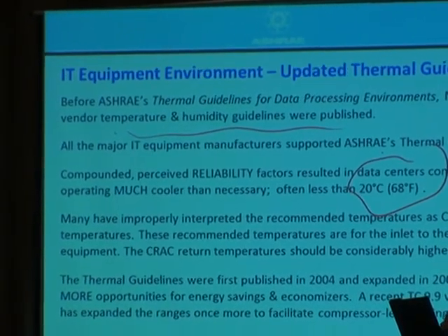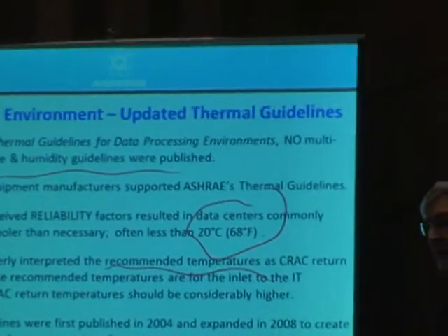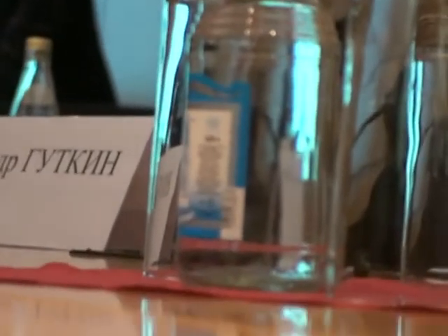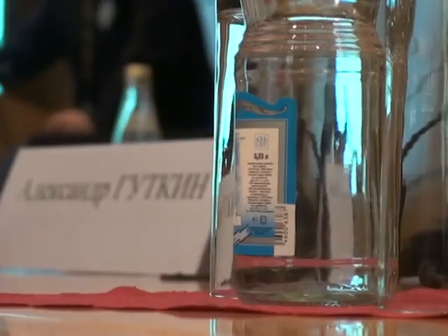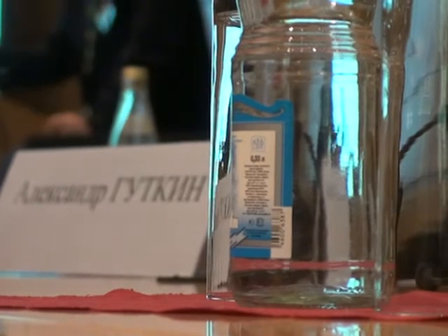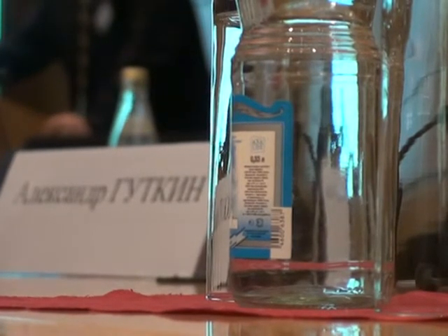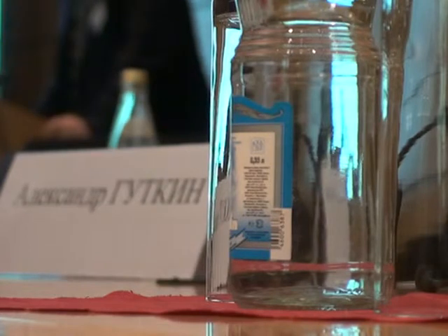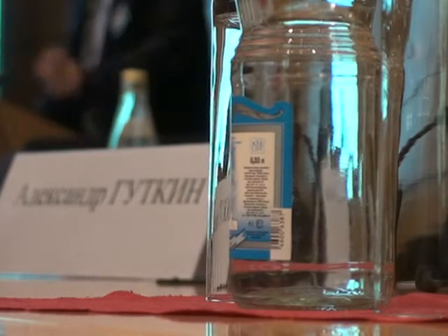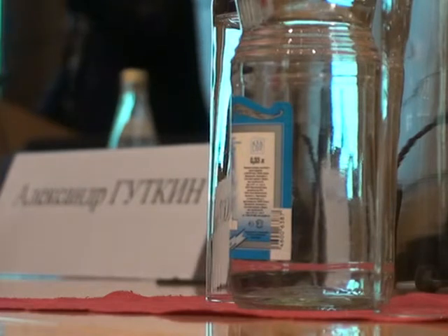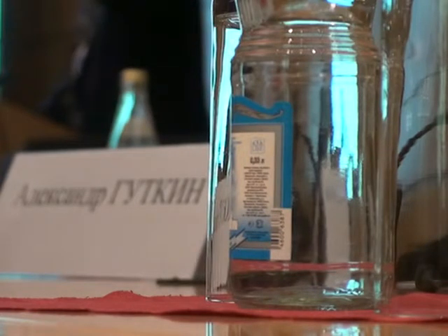We'll talk about recommended temperatures. Again, where are the recommended temperatures located? And I'll talk to where that measurement is, and that 27 you talked about. So 2004 the first time, 2008, the new one will be 2008. So here's the new one. I'll just start. Recommended is 18 to 27. Again, all the IT manufacturers agreed to this. Legacy equipment or new equipment. Legacy or new. 18 to 27.